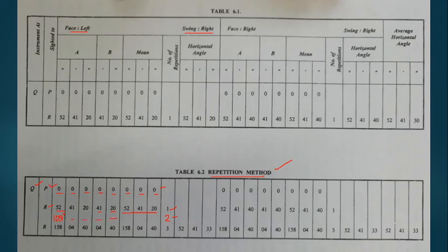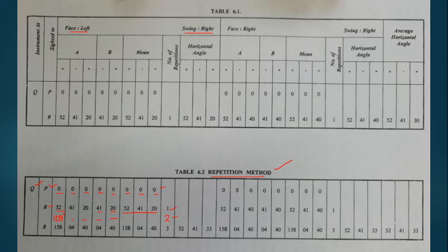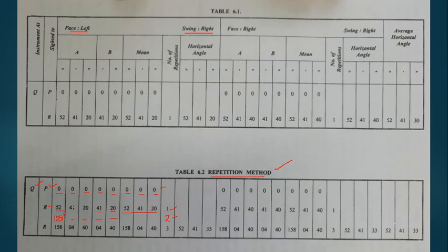Okay, right, we'll go back. With vernier A, I have taken the main scale reading and vernier scale reading. It may be something like this. And in vernier B also, I need to search for the vernier coincidence only. And for that coincidence, I need to add the main scale minutes we have got in vernier A. Just like we have got 40 minutes, and here only 1 minute and 20 seconds, but still I need to add 40 here. Similarly, a similar kind of thing applies here also.